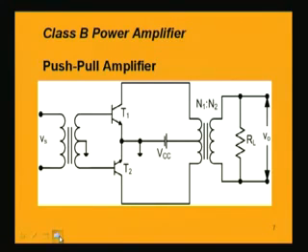We have two transistors here, they are shown as T1 and T2, and we are having transformer stages both at the input and the output. One example we are showing where we are having a transformer at this input stage and another transformer at the output stage, and the resistance RL is connected to the secondary of the output stage transformer, and the voltage across this RL is V naught, which is the output voltage we consider for driving any load.